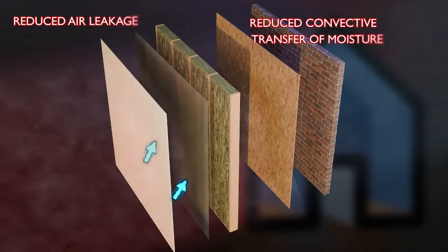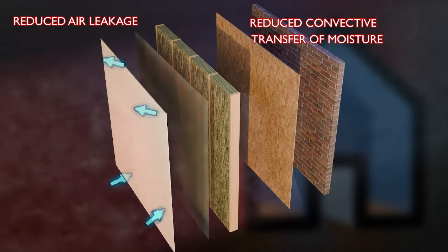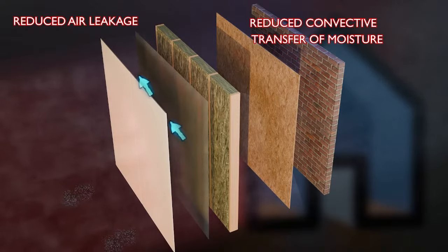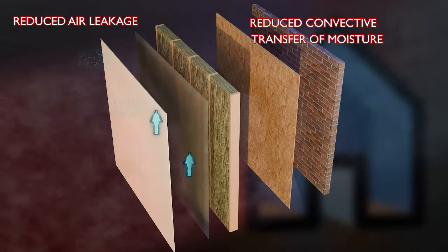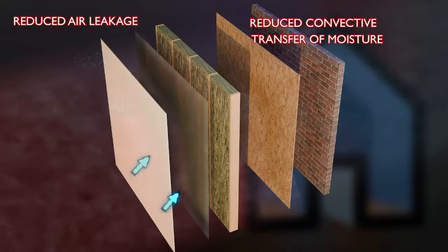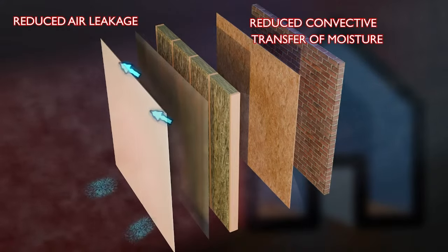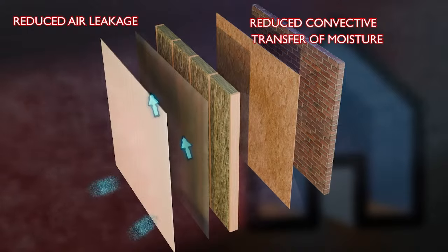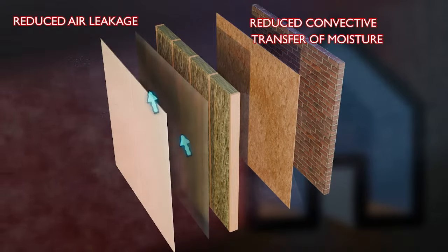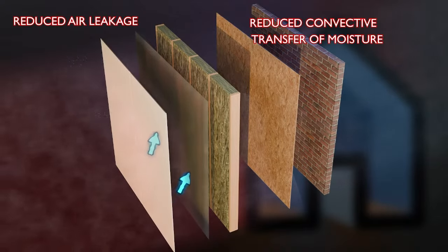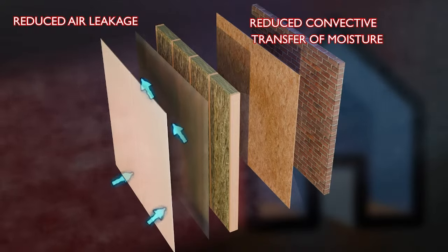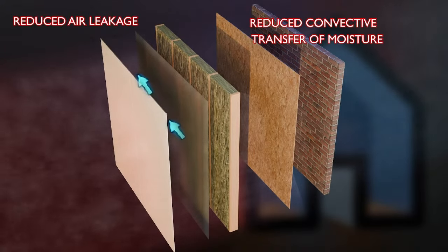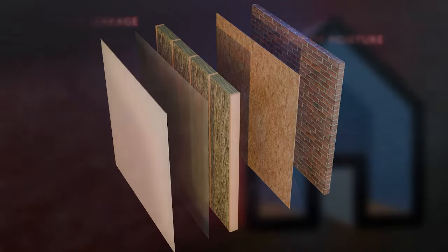Secondly, by minimising the convection associated with air leakage, the AVCL reduces the possibility of air movement transporting moisture into colder parts of the construction and creating a localised condensation risk in the area. In modern buildings, convection like this can usually be attributed to as-built or ABIS issues such as unsealed joints or penetrations. Due to current air leakage requirements, most buildings are designed to be convection tight, so any air movement through the fabric is likely to be due to a defect of some sort.